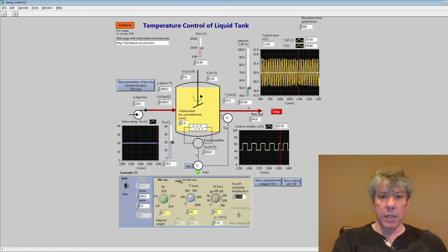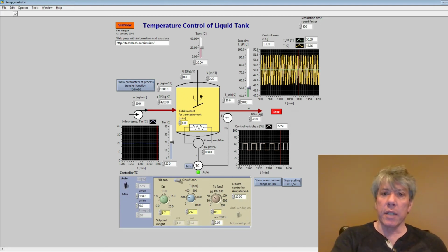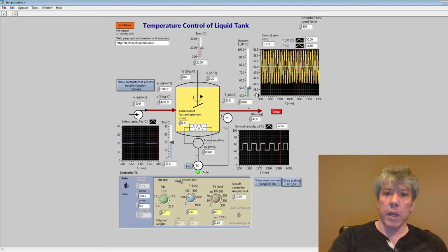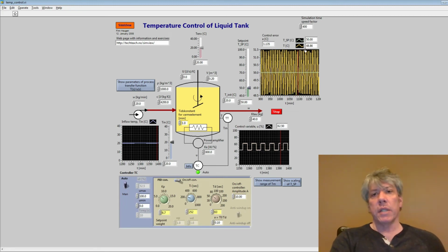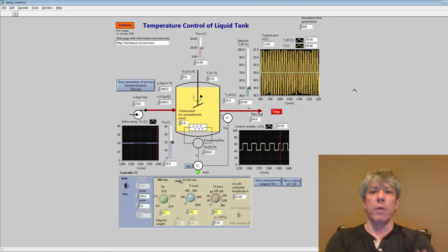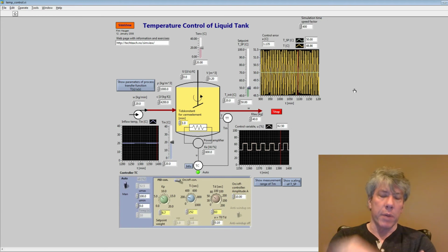Well, it looks like it varies just a bit, but it's really not too bad. Let me see if I can zoom in some more even though it's not running. Yeah, it looks like that works. 51.5 degrees. There we go. This is looking pretty good. 48.5 degrees. There we go. So it looks like the temperature varies between about 48.5 and 51.5 degrees. But I need that as a percentage of the range.